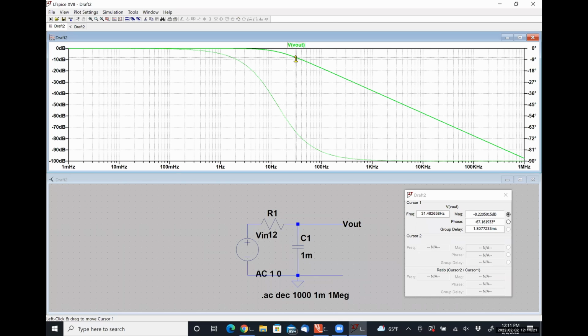So 60 dB is generally accepted to be the largest reliable attenuation that we can get. That means we've attenuated the signal power by a factor of 1,000,000, and that's usually somewhere around the maximum resolution of what our measurement device can reliably do.